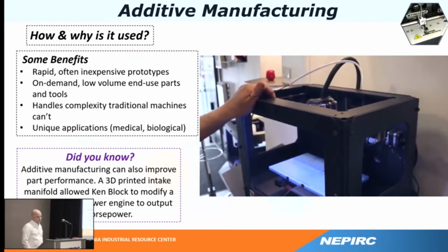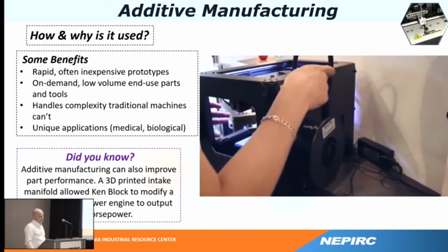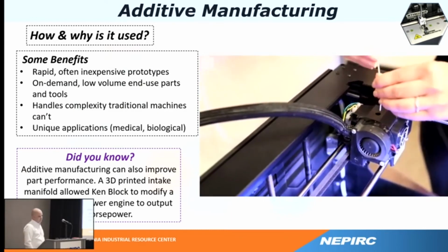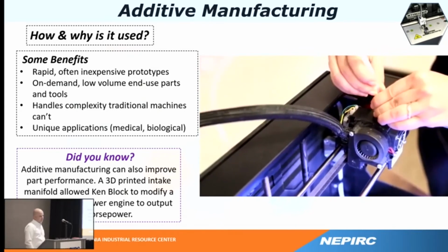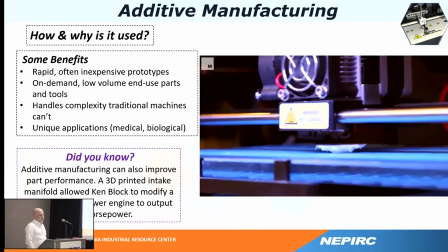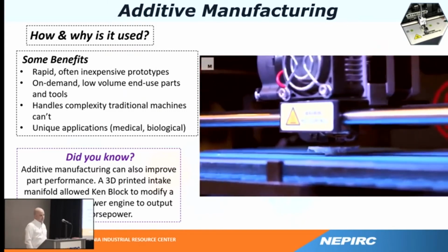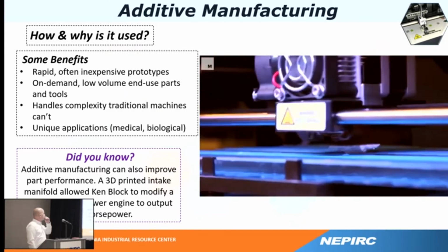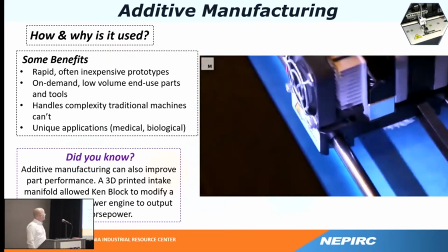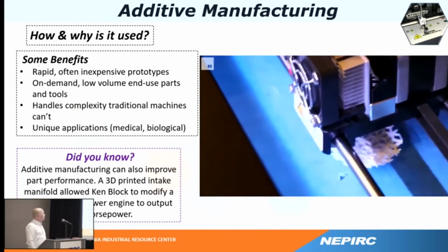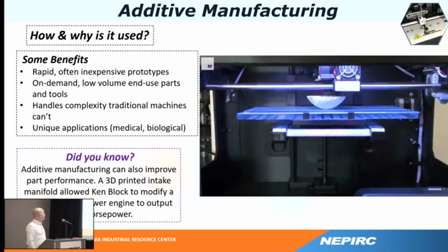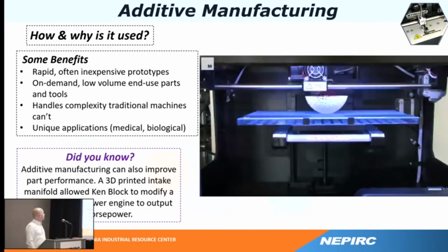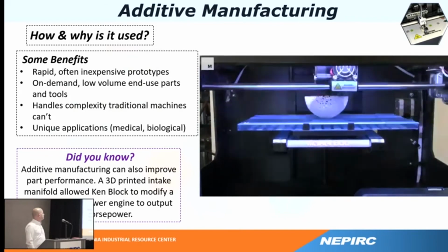Some printers, like the MakerBot Replicator 2, have renewable bioplastic spooled in the back of the device, almost like a string. When the printer receives the data, it pulls the material through a tube, melts it, and deposits it to the plate where it instantly cools. As you can see, the 3D object is created through layering, where the printer will add one layer of the object at a time until you have a fully formed structure.